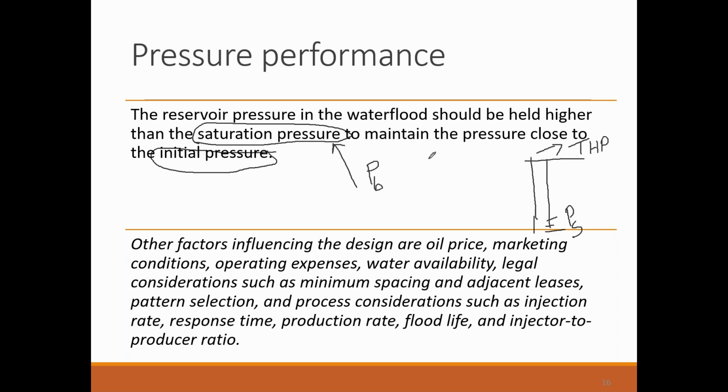If your THP is constant and your production rate is also constant, then there are no worries. But if your THP is declining, then you need to measure the static bottom hole pressure. And if you are not able to measure it, then you should use some correlations. You can take THP and use the vertical flow correlations, and try to add up to reach this particular point. You can estimate this PWF and have some estimation.